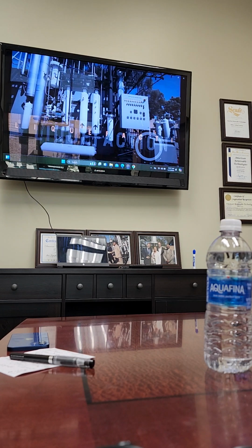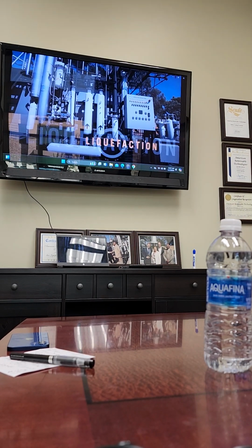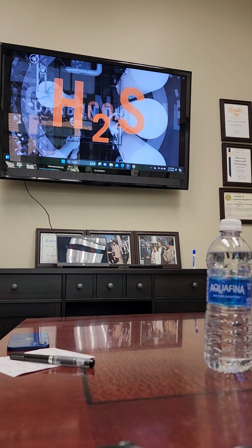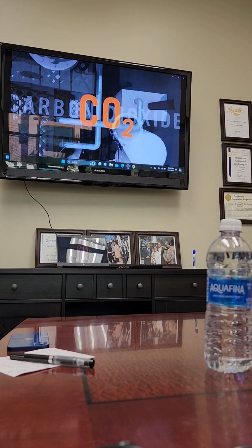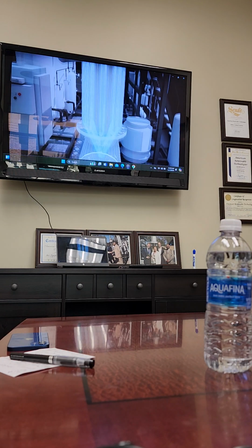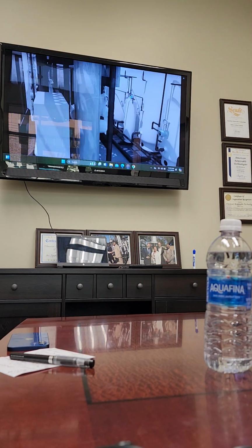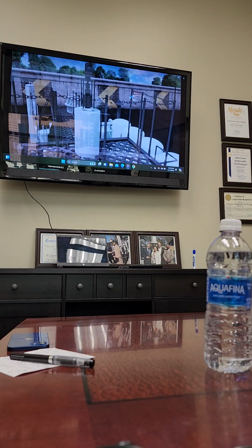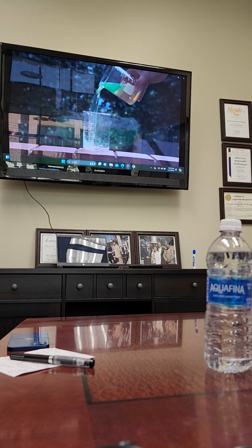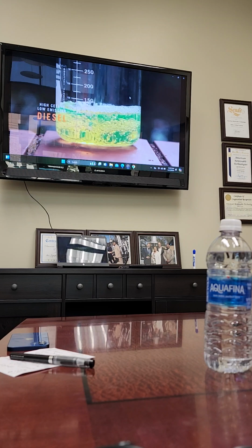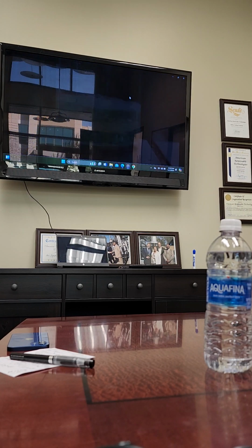The second part of the system is called liquefaction. During liquefaction, the pyrogas is preconditioned by removing hydrogen sulfide and carbon dioxide. It's then reformed with steam in the presence of a catalyst into a synthesis gas. The final step transforms the synthesis gas into a liquid fuel by recombining the carbon and hydrogen into long-chain hydrocarbons. The end product? A high-cetane, low-emission diesel fuel.